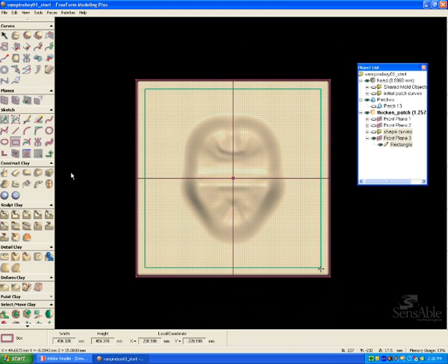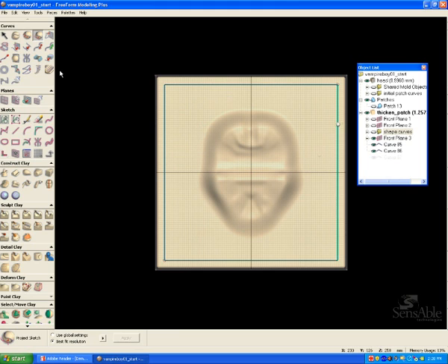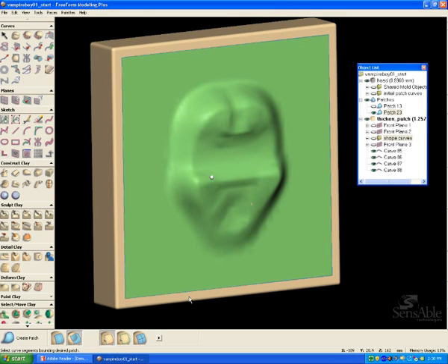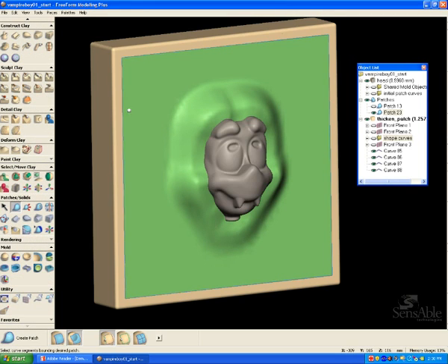So now I can take a new sketch plane, and I'm creating a square to set up the boundaries of my parting surface so I can project them to the clay. And what I'm doing is I'm rebuilding the curve networks to give them a lot more points so that there's more points for the patch to fit to.